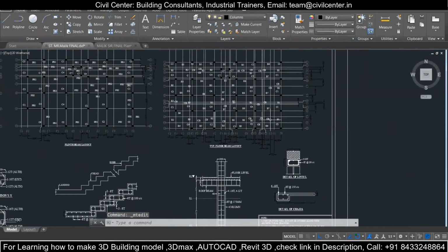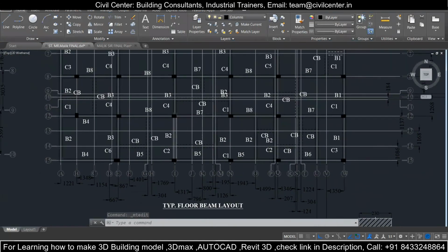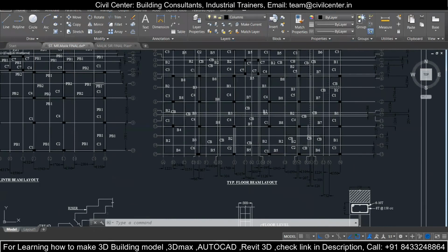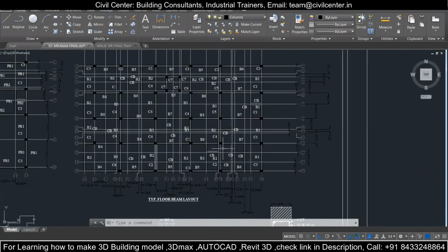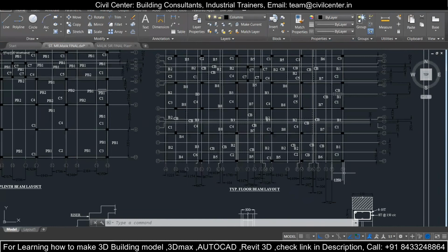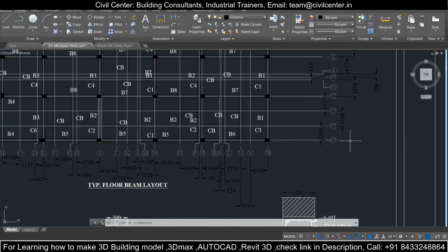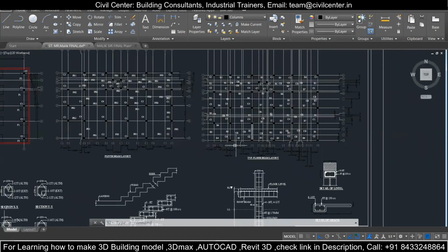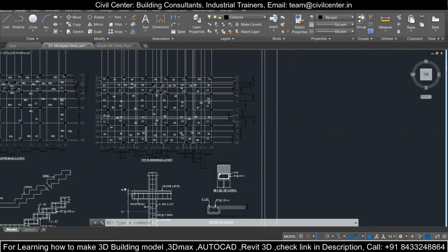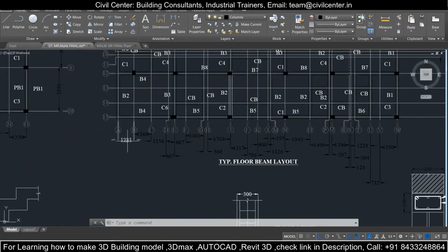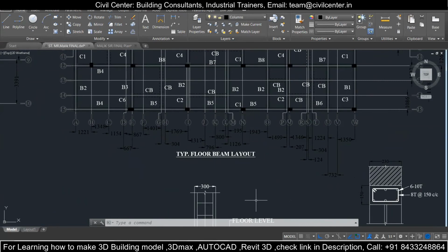Grid lines till W over here, and in this direction, that is in the Y direction, we should have the grid lines from 1 to 15. So I am going from bottom to top, so I will simply change it from bottom to top, it should be 15 14 13. So I will simply name it like this. Okay, so let's see how we can do this. Okay, so first of all let's work in the x-axis and we have to go till W.